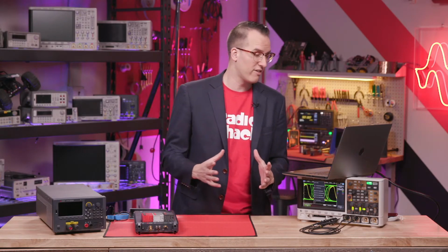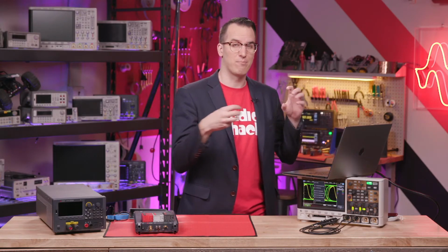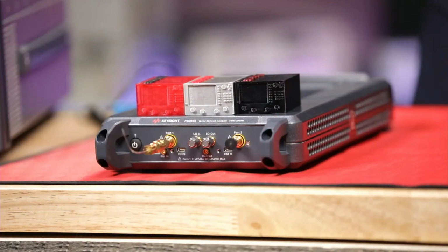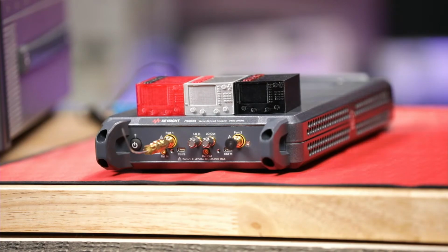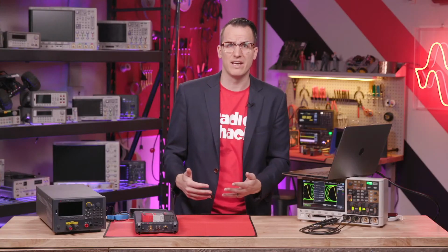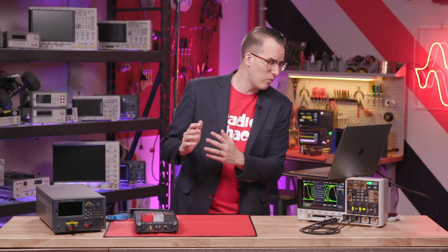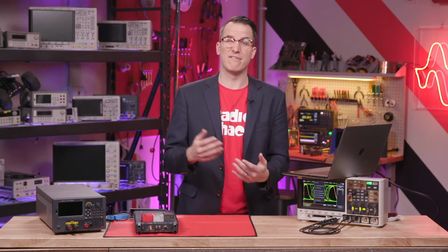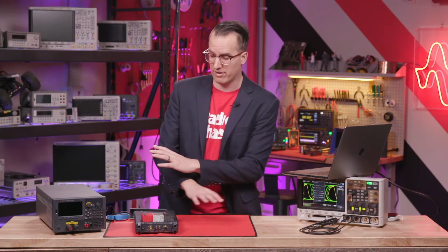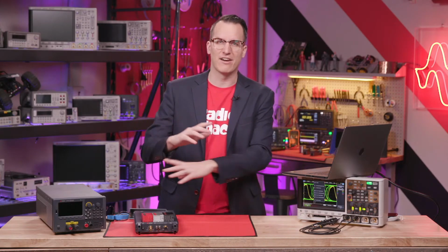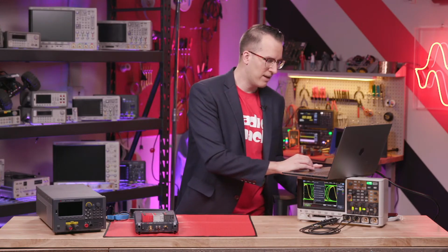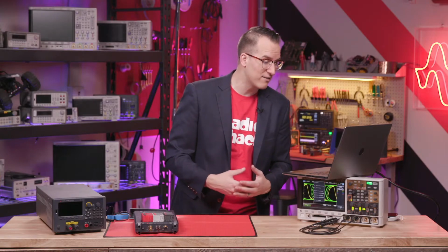One of the things Joel said is that you should think first, pre-measure, and then calibrate your VNA before going to do a full setup. And someone said, I didn't know that. I always calibrated my VNA first. Joel's response is that older analyzers didn't have a very good factory calibration, basically how they came out of the box without calibrating, because conventional wisdom says you should always calibrate your VNA before you do anything. He says older analyzers didn't have good factory cals.